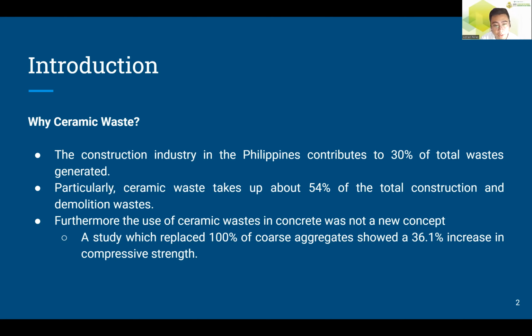The results of one study have shown that 100% replacement of coarse aggregates yielded a 36.1% increase in concrete compressive strength. Despite this, the viability of ceramic wastes is affected by its high absorption capacity. With this, the study aims to apply aggregate modification treatment methods to investigate if the absorption of ceramic tiles can be reduced and to determine its effect on concrete workability and strength.